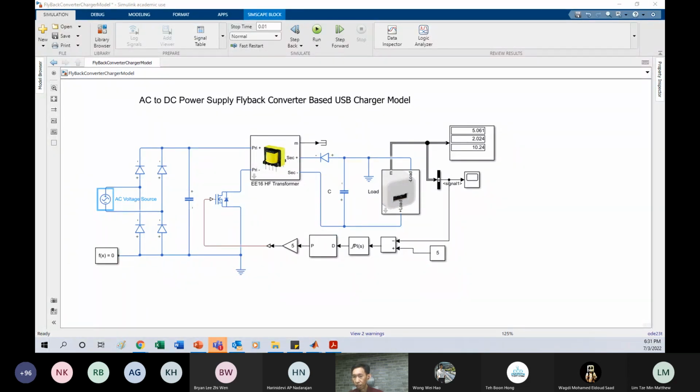Okay, good. You just designed yourself a 10 watt power supply. So you just change this to a higher power, then you can make yourself a fast charger. So far, I think in the market it's 33 watt, right? Anyone know, is there any higher? I'm pretty outdated, I would say. You want to beat the fast charging, of course, the problem is you have to tell the factory that makes this transformer, I want this transformer with this ratio.